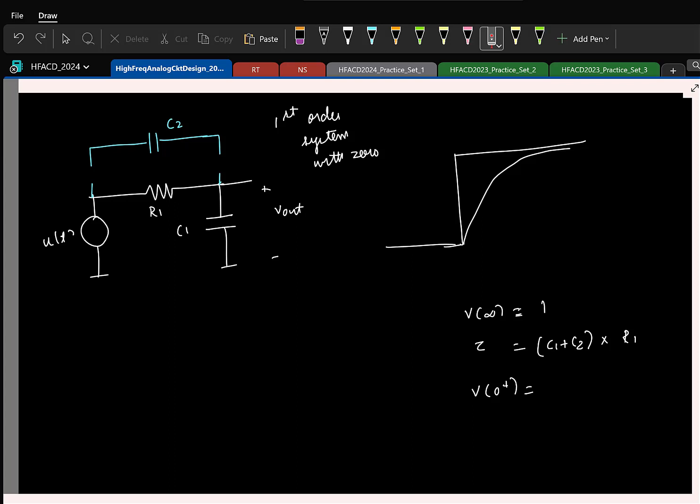Okay, if the capacitor voltage has to change instantaneously, how should the current be? In this case, the impulse current can only flow here, which means the voltage across the resistor has to be some impulse. But nowhere in the circuit do we have impulsive voltages. Everything is a step. So simply you can contradict that.